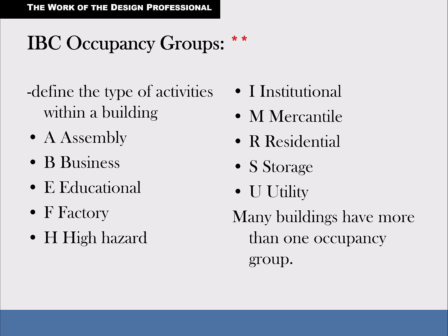So if you had people in a hospital that maybe can't escape because they're bedridden, well, it's going to take longer to get them out. So the buildings that are institutional have to be made primarily of concrete. And you say, what about steel? Well, you can use steel, but steel does not fare well in a fire. It fails. That's how the Twin Towers collapsed. They were steel buildings without proper fire protection. They had inferior fire protection. I can talk about that more some other time.